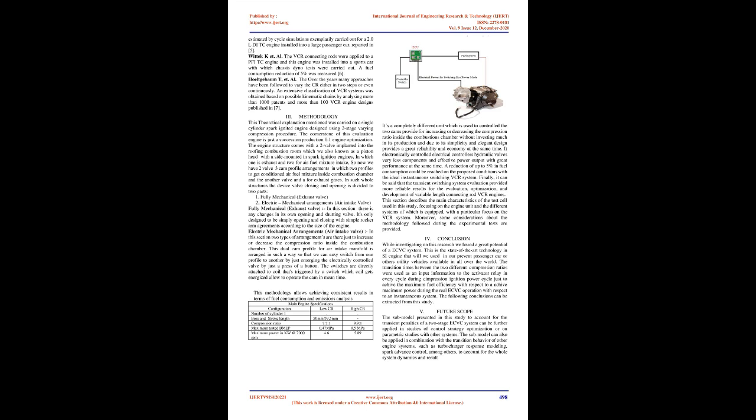If the compression ratio is also adjustable, as is the case in a variable compression ratio engine, then this reduction potential could be exploited. The fully variable compression ratio systems offer the highest flexibility and so the greatest thermodynamic benefit. On the other hand, many of the approaches require a completely new engine architecture, causing high investment in brand new manufacturing lines. Nissan Motor Corporation has just launched a new engine featuring a fully variable compression system for their next generation engines. 2. Literature Review.